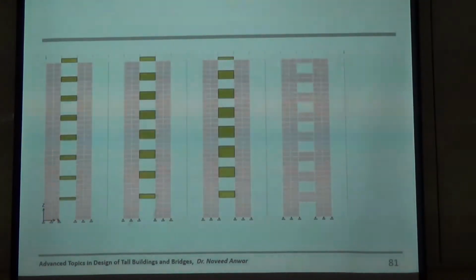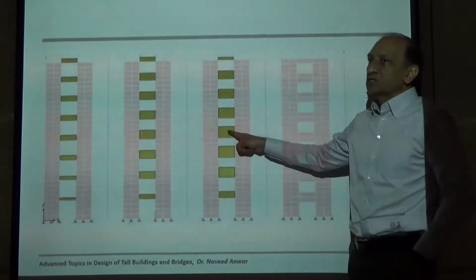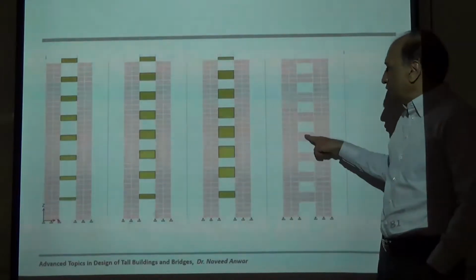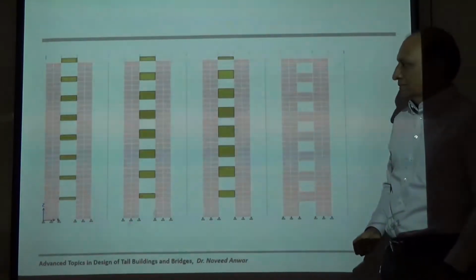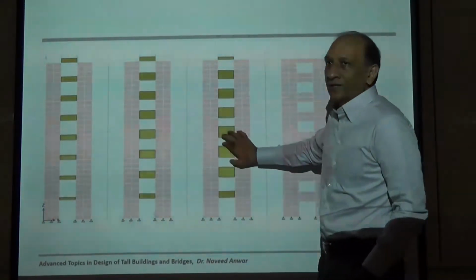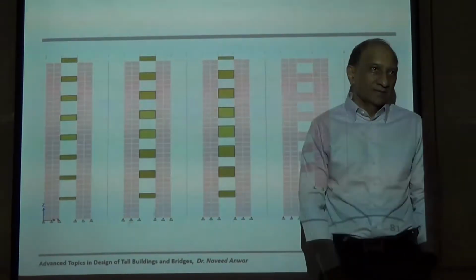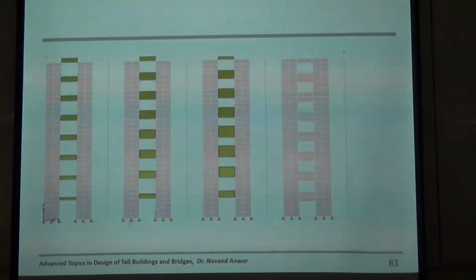So that is the shear. So that's the advantage of using line element, that you can get all these forces easily. Difficult to get them for area element unless you put section cuts. So you can see shear increase quite a bit. And if the shear capacity is less than that, we don't want it. So we have to limit it based on the shear capacity.